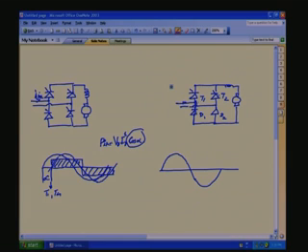So, during the portion when this point goes negative, there is a short circuit through this path, and the output voltage will be 0. Now the current waveform: during the freewheeling period, the input is not giving any current to the output. So, at that point it will be 0, then here this way it will come. Then the input current waveform is like this. This we have talked about in the last class.